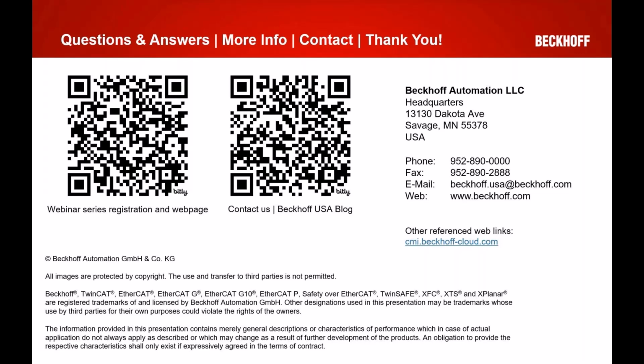How to set alarms in the HMI, the easiest way. The easiest way would probably be to use the PLC functionality that TwinCAT has, which we call the event logger. It's very much drag and drop. The event logger is pretty much automatically tied to the runtime system on your target, and it just works. Then you throw your events and alarms through your PLC logic.